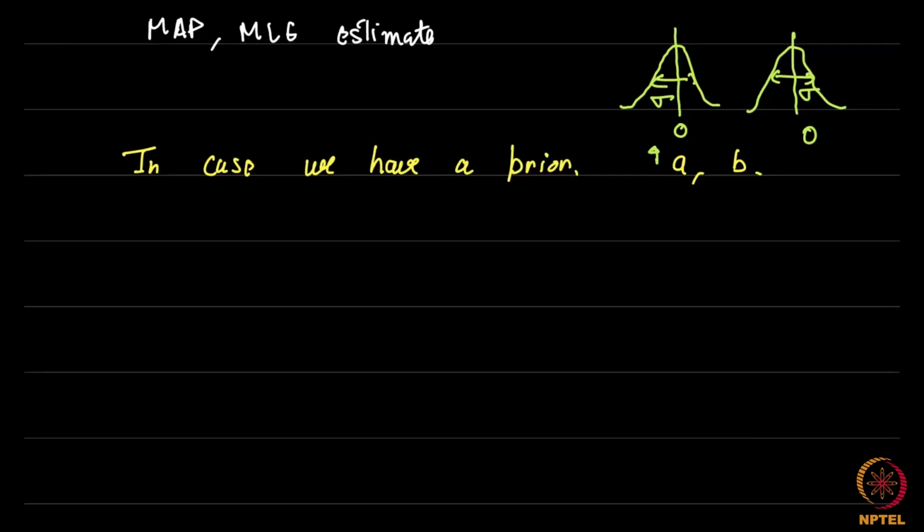So for example, let us say we have conductivity and we know that the K is one of the parameters we are estimating, and let's say we know it is made of steel and it is going to vary between, let's say, 50 watt per meter Kelvin to 55. Okay. If we have some such estimate, then you know that you can sort of fit. I again request you to go back to the examples we did in the previous week, for example, for the pipe, etc. So all these cases have some mean and some standard deviation. So the special case that I'm taking here is, let's say we have two parameters where the mean is 0 and the standard deviation is, instead of calling it sigma, let me call it beta.